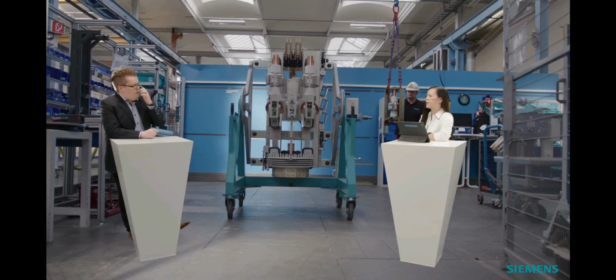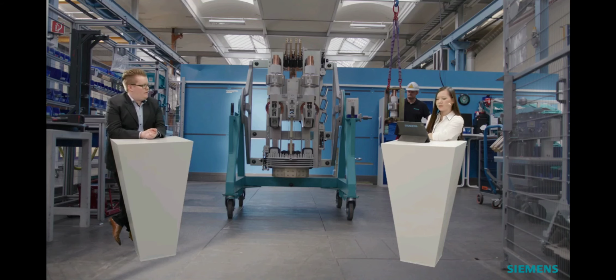Okay, so the 300 is given by the standard, or is this a Siemens specific value? The 300 volts is given by the standard. This is the minimum value. So when we are using the 300 volts as given by the standard, we are still calculating the absolutely worst case. Okay, interesting. Can you give more insights on out-of-phase calculations?